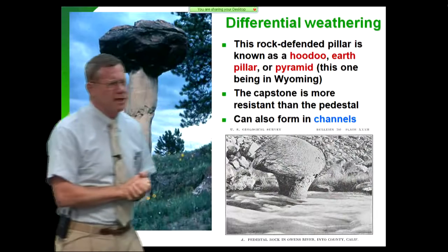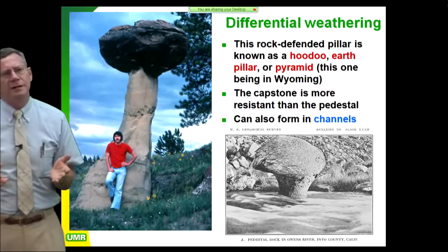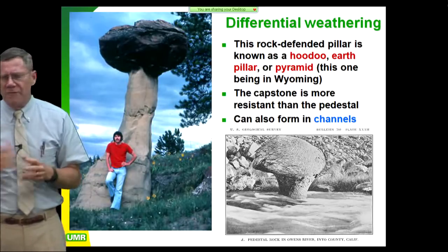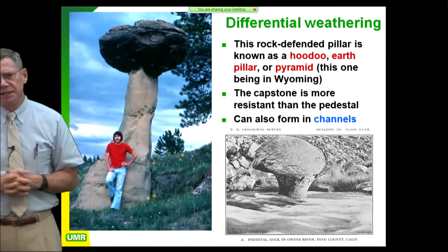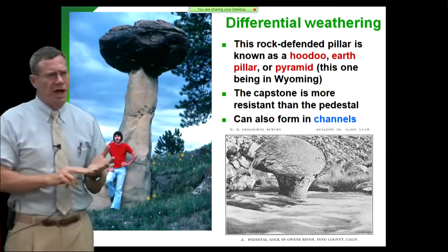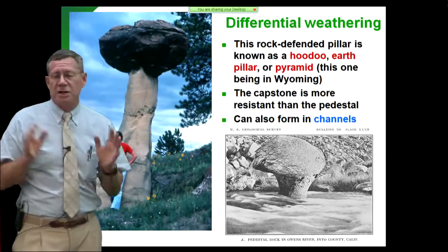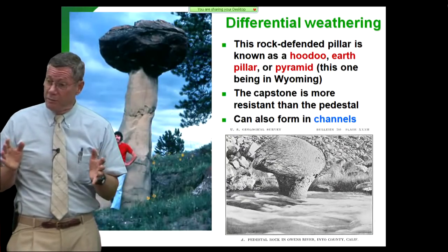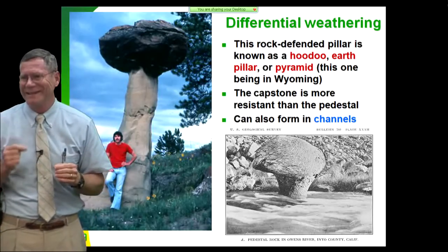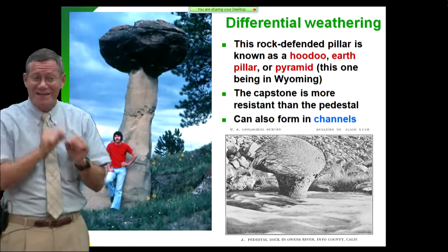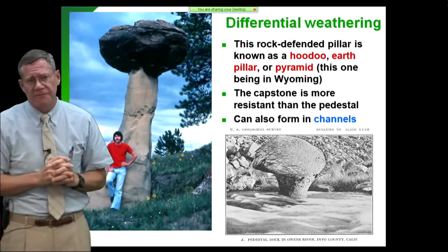Differential weathering is something you always want to be on the prowl for. You always want to be observing it as you drive by, as you go out on the freeway. If you have different stratigraphic units, you're going to have differential weathering generally. And differential weathering isn't just the lithology of the unit, it's the intensity of the jointing. Things that are brittle, like siltstone and shale, believe it or not, are intensely jointed. So they tend to erode more easily because you're divided up into smaller blocks. Doesn't take as much pore pressure to push those things off as it does a big block.